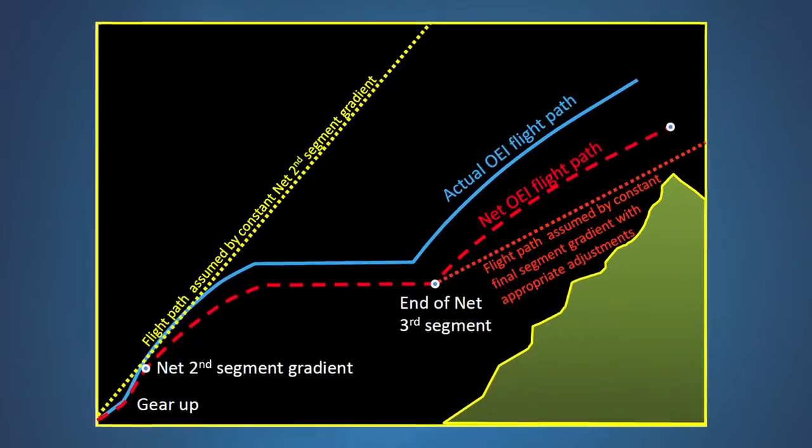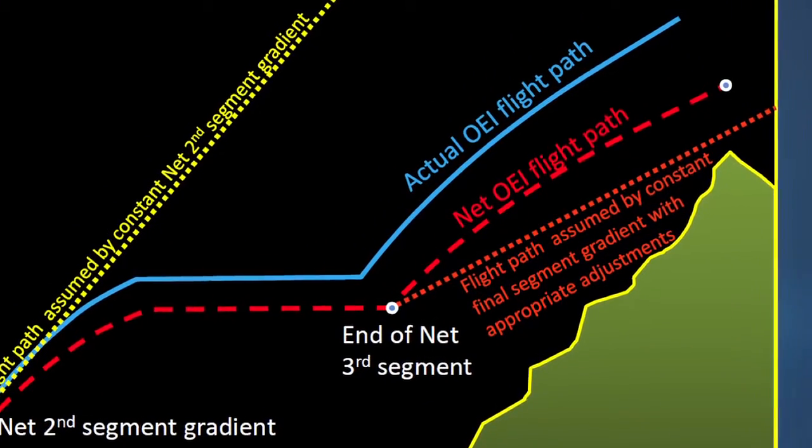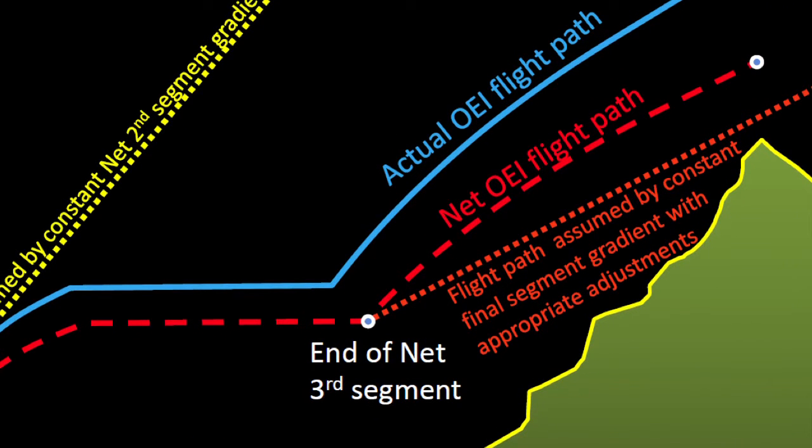The final segment flight path does not have any large discontinuities in it since the configuration is constant throughout, unlike the initial portion of the takeoff flight path where the gear is in extended position in the first segment and in the retracted position in the second. The combination of these factors make it possible for determining a conservative gradient based on the distance to the obstacle for use in a rise over run obstacle analysis from the end of the transition segment through to the end of the final segment.